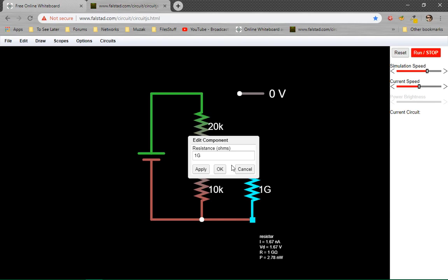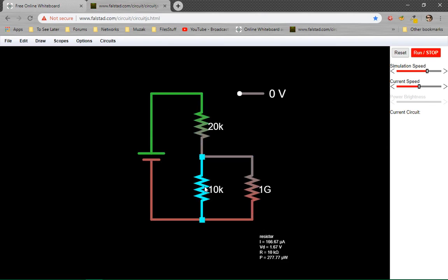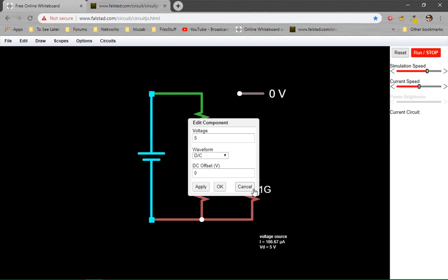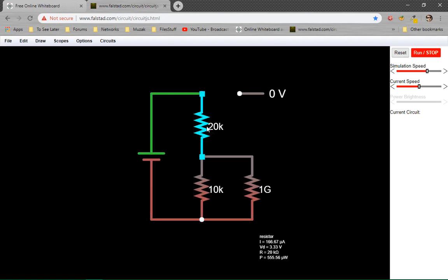This amount of current doesn't give us enough power to tell the difference between some action the circuit is doing and random noise all circuits have. Yeah, this one, it's actually 20 and 10 kilo ohms is kind of high for a 5 volt, but it pretty much works.